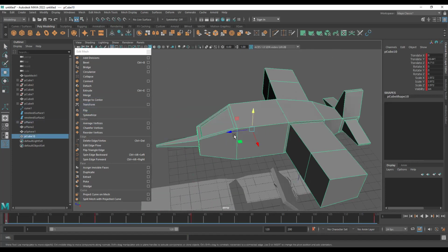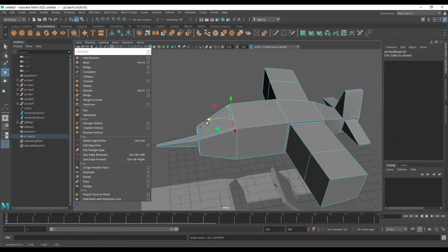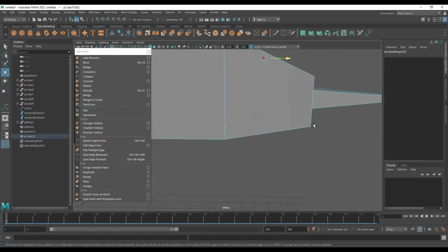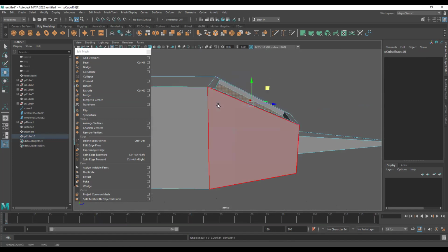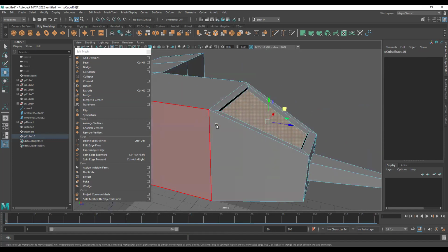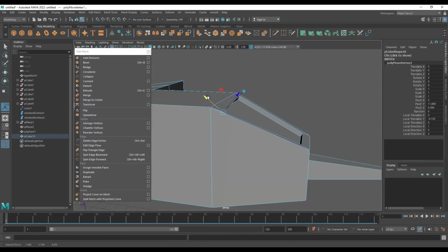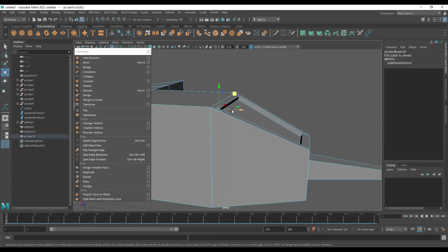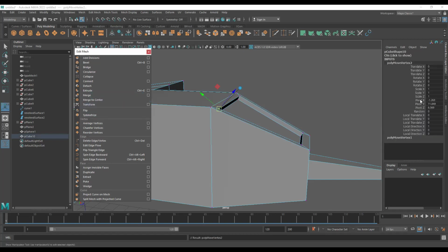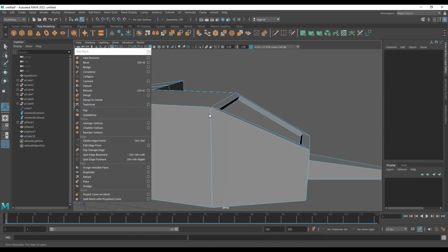Next is transform. Transform is nothing but select and move. What do you mean by transform? Transform is just like moving. But here the transform actually works according to the direction of the normals. If you click a transform, you can see the direction is changed. So there are two types of direction, one is global and the other is local. With global direction, we are moving it. And when you click on the transform, the local direction will change. You can see the pivot position is rotated.